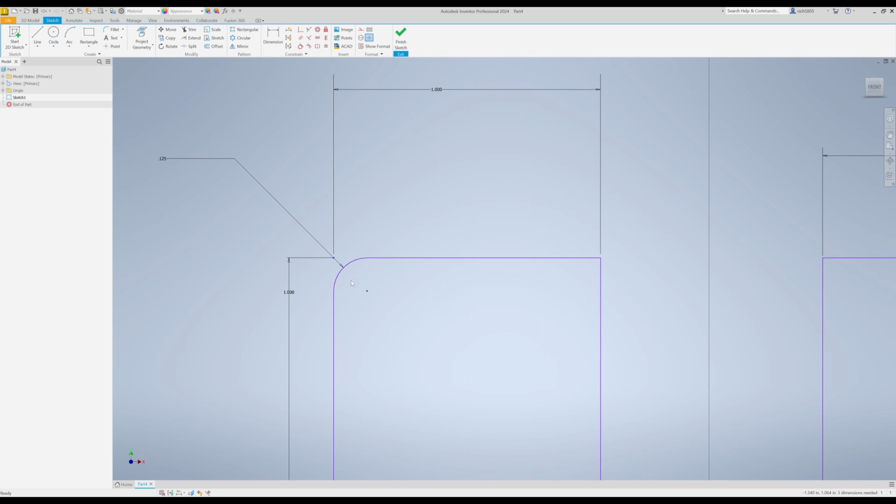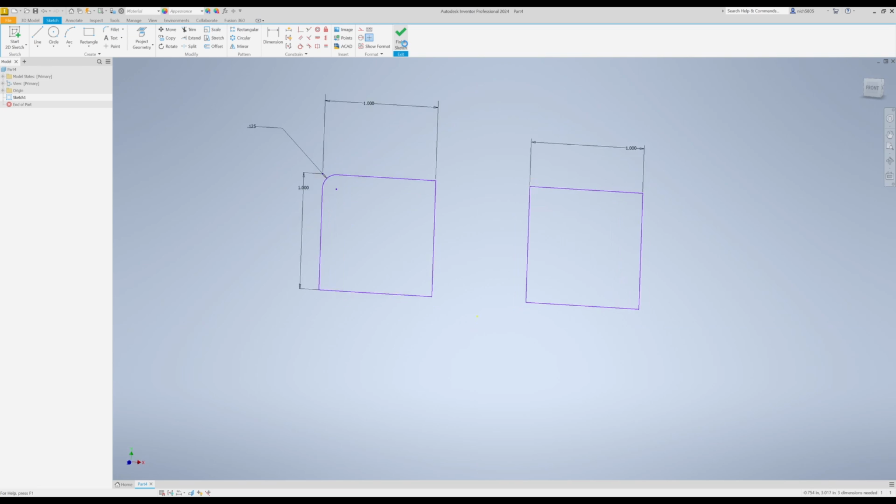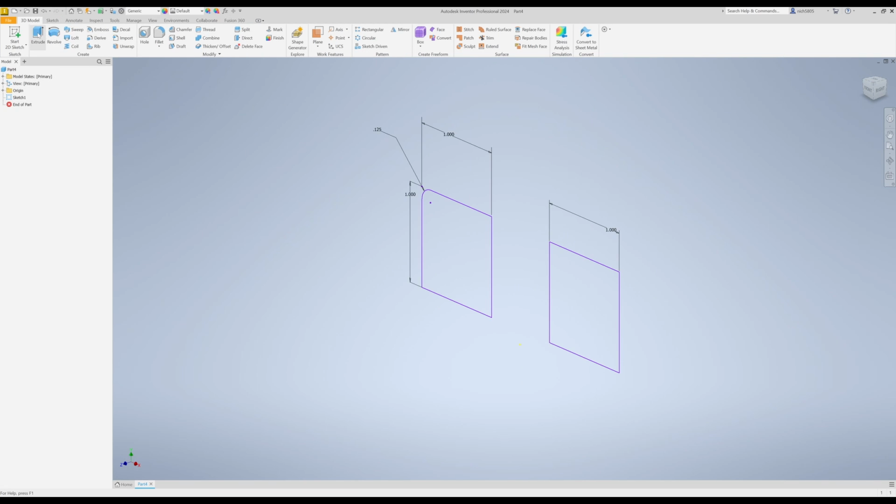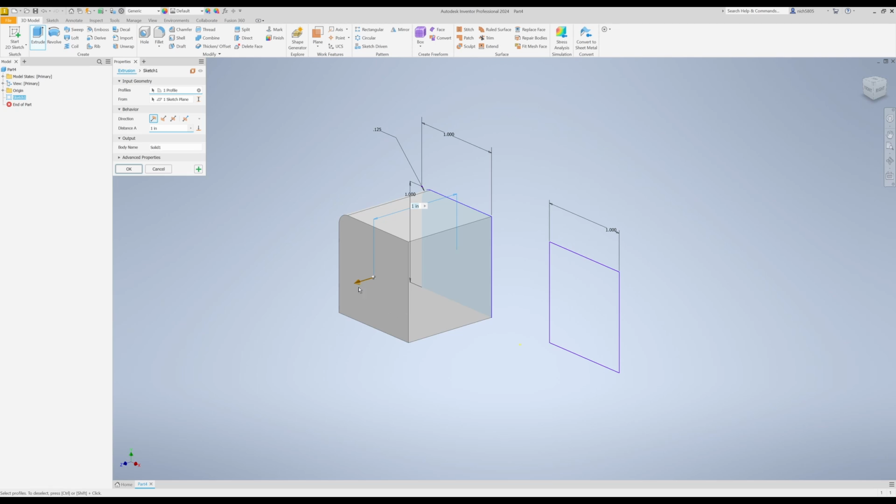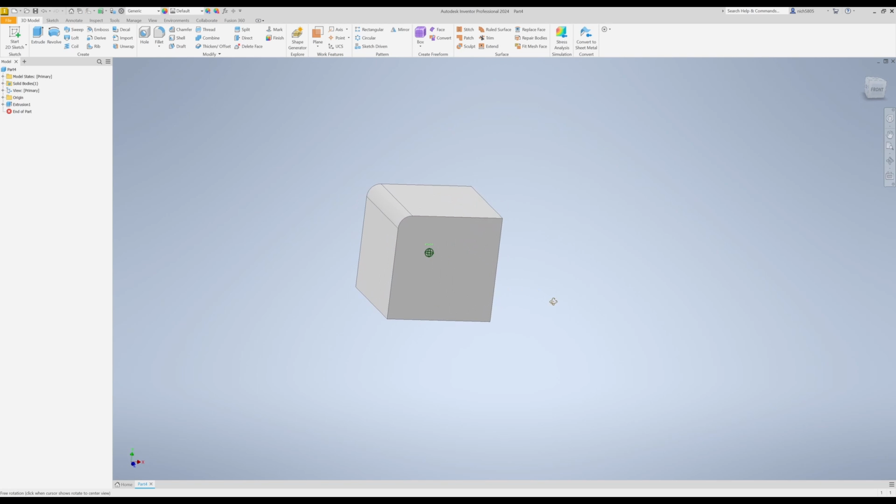And now, this fillet is measured out in a certain way. So let's click Dimension tool, and let's click this point right here, and this point right here. This dimension right here is 0.125. It's going to be from this line up until where this curve stops. Let's delete that real quick, and let's finish our sketch. If we were to extrude this, it would come out looking like this. We would have a fillet on this edge. I'm going to delete that real quick, but keep our sketch.